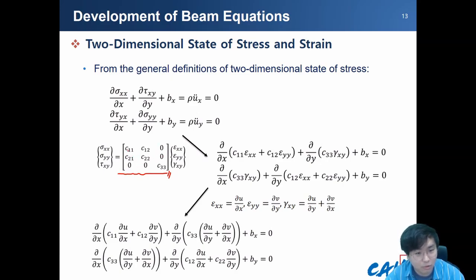The diagonal terms have some specific values, and also the elastic modulus in the shear part has a specific value. However, this off-diagonal shear part is always equal to 0, so this is a more general form of the 2D elastic stiffness matrix for 2D cases.